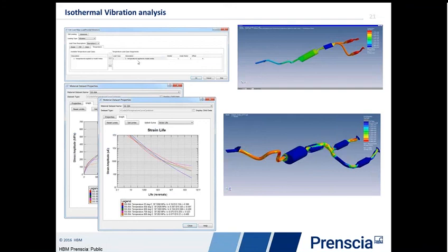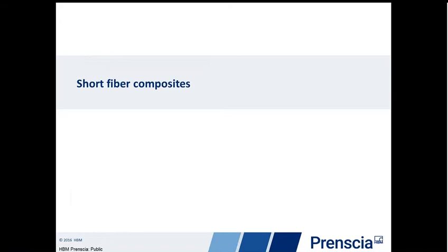And in terms of material properties, we've brought in not a single strain life curve, but a whole family of strain life curves at different temperatures. So I can do isothermal fatigue analysis in the frequency domain with this. Again, this gives me the ability to use my frequency-based loading and apply more low cycle fatigue behavior.